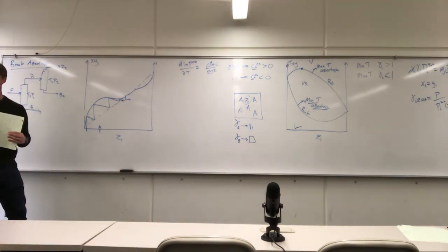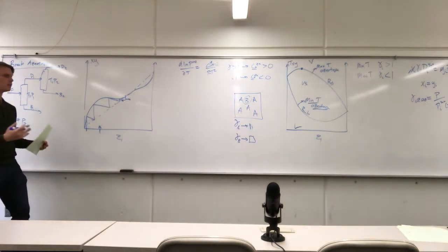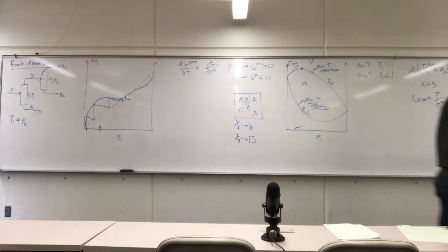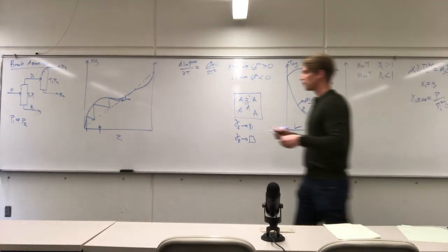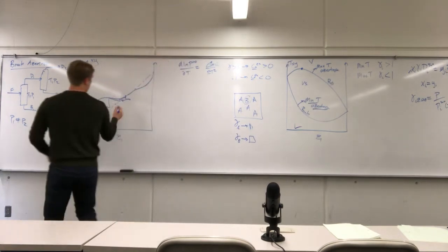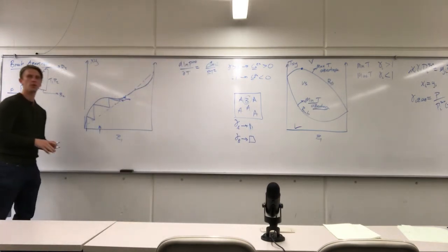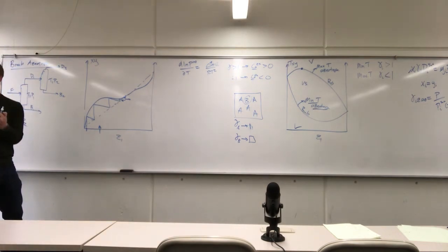So the objective, in doing a pressure swing approach to breaking an azeotrope, is that in your first column, if you can distill it to very near to your azeotrope, what you need to do is shift the azeotrope enough that you pop out on the other side.